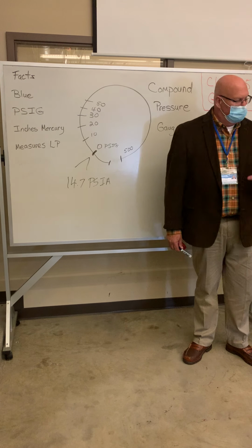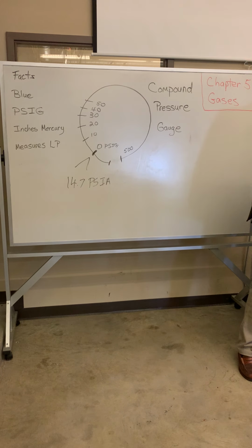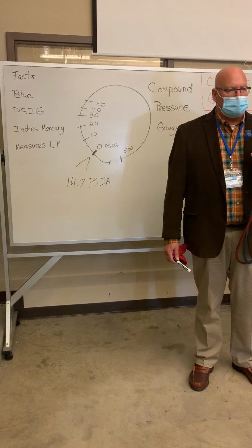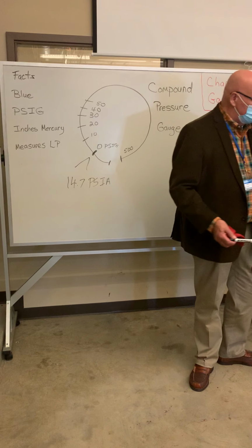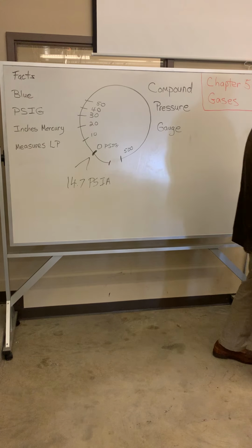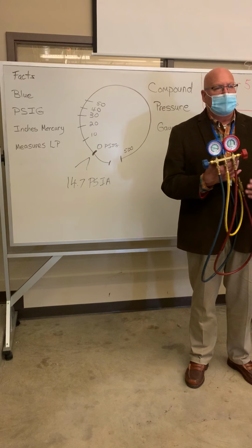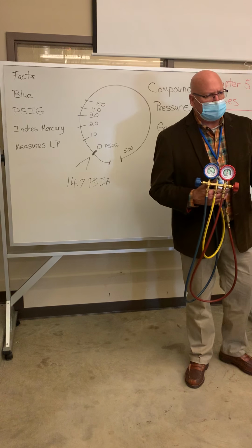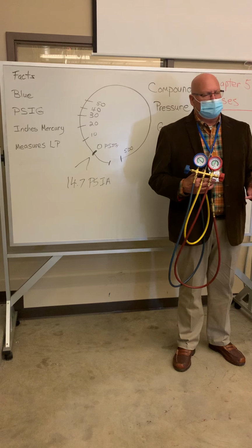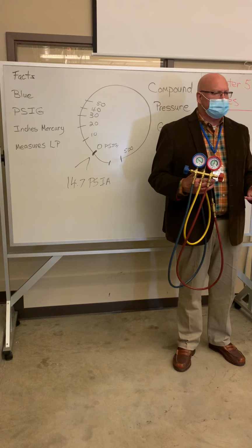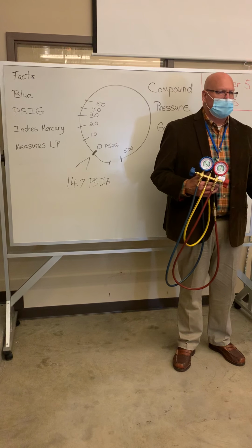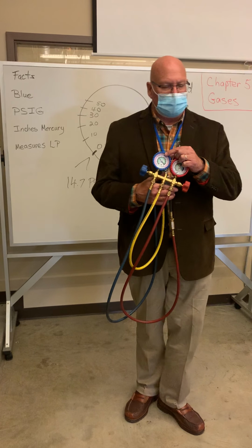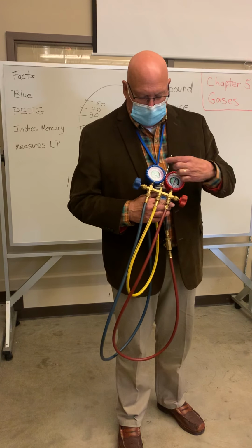But I want to make sure you realize that this gauge, when at 0, actually means that there's still atmospheric pressure there. When we start to remove atmosphere from a unit, then it will go into a vacuum mode and it will be less than that 14.7. Generally speaking, in mechanics, we usually don't get into all these decimal places. We'll just call it 15. It's close enough.